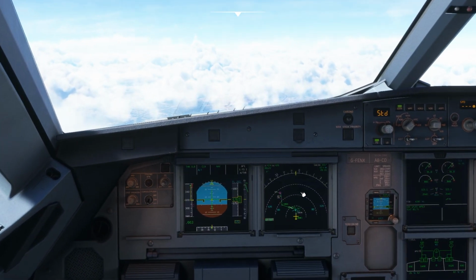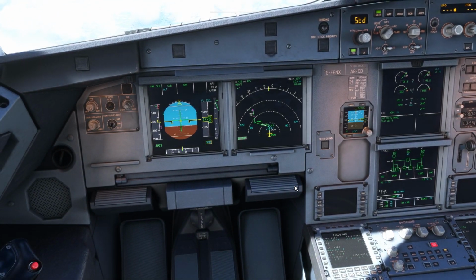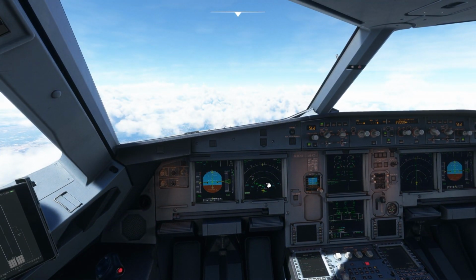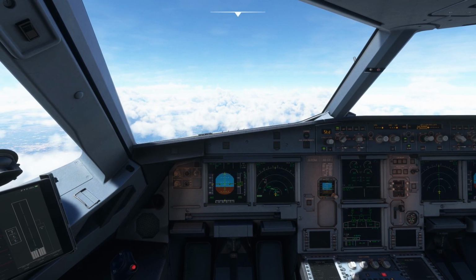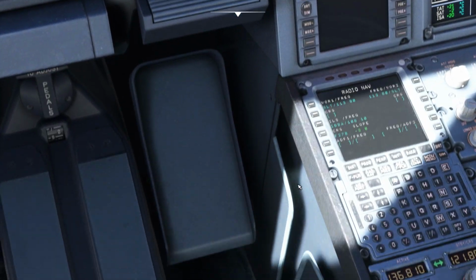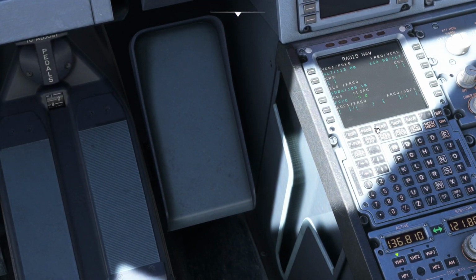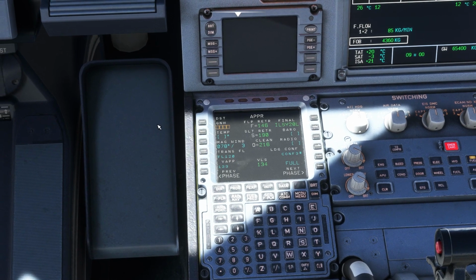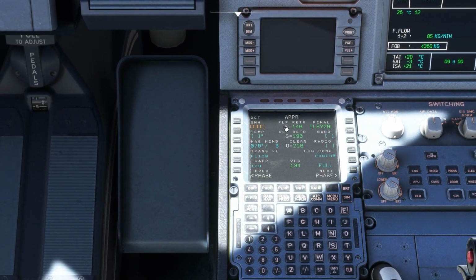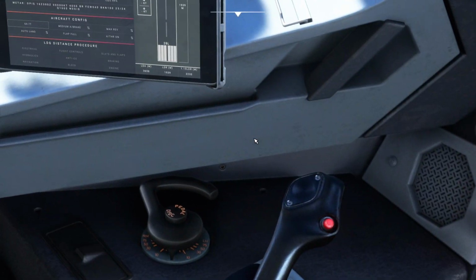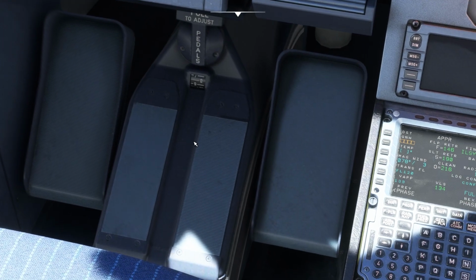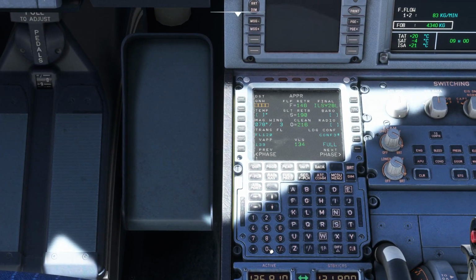So after doing the landing performance calculation, there is some turbulence over here. Okay, so let's get to this tab in the MCDU performance. Scroll through the pages, go to next phase, and come to this option, approach. We need to enter this information for the QNH. We can get this information from here as well. It's given, it's 1005.